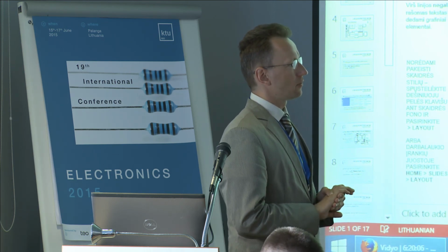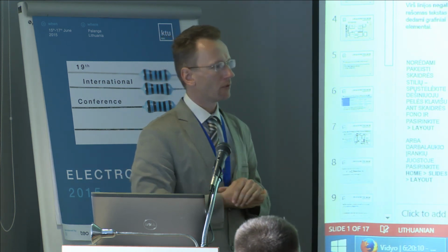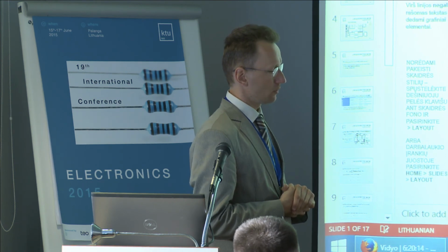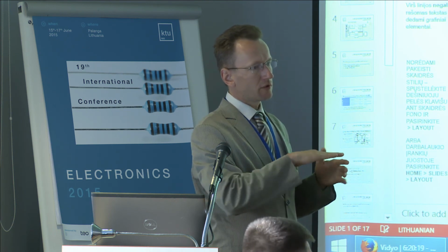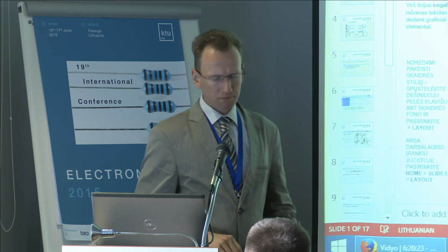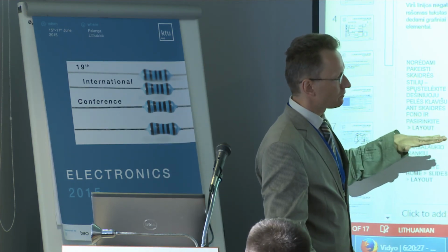About the frequency or period measurement, and which samples we collect for averaging, that implementation was based on thresholding, not zero crossing, but a 1 volt reference, which is internal in the microcontroller.